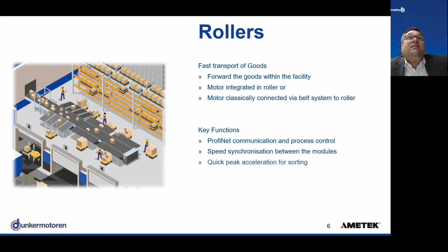The functions also communication, because the rollers need to be synchronized in speed, and when there is an outfeed of the parcel which is not with a hinged system but with a roller system or with an angled transport, then you have to speed up the parcel in order to keep an equidistant between the following parcel, so that they do not crash into each other.